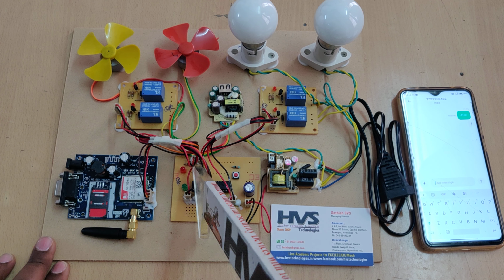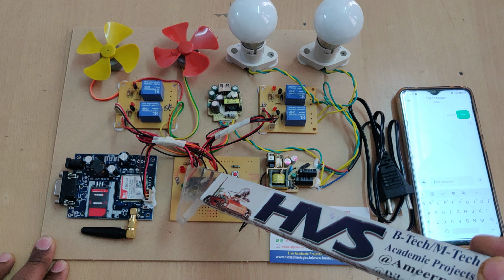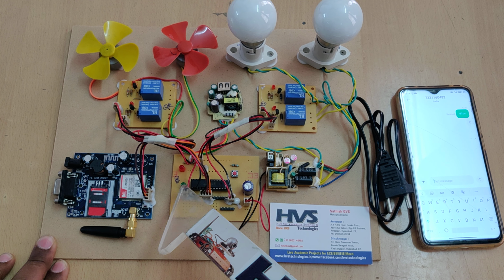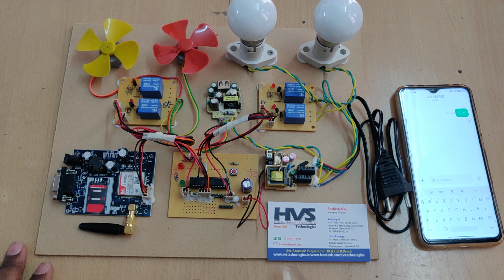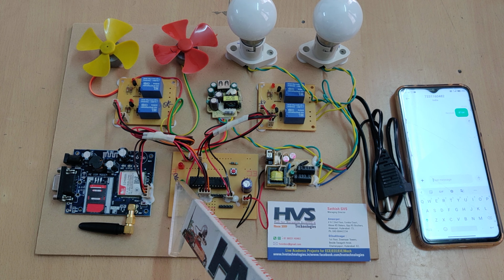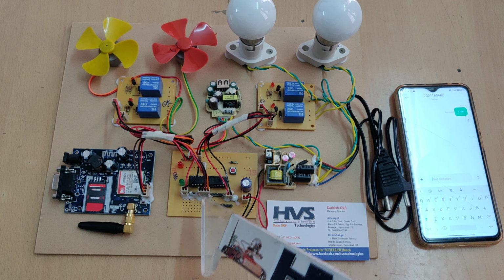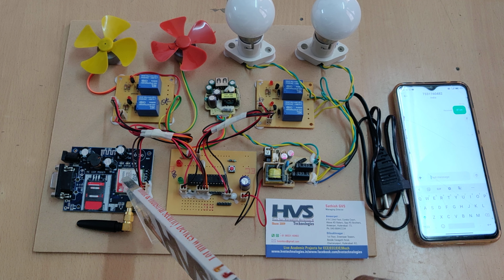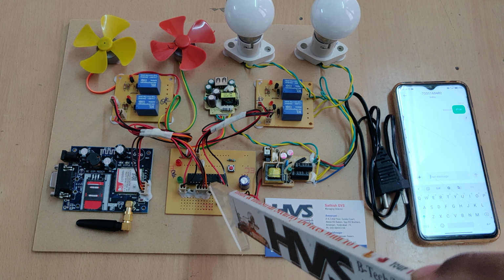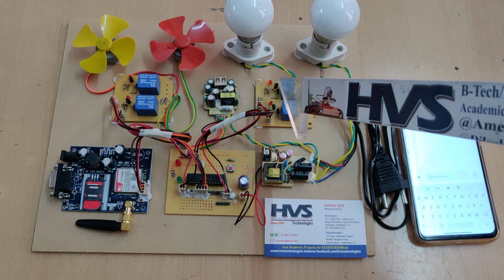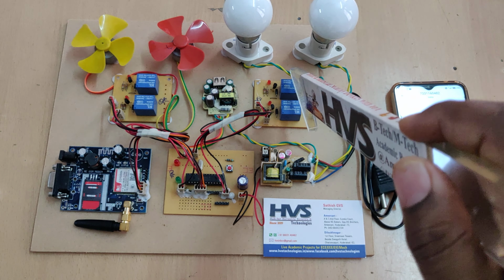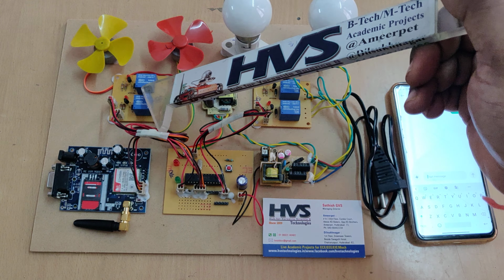And coming to this, the red LED is the power LED indication, and the green light is the program LED indication. Based on every loop, this light will blink and show us the status of the kit working model. Next, the GSM modem is interfaced to the motherboard at the B0, B1 pins, and these 4 relays are interfaced at C0, C1, these 2, and C2, C3, these 2.